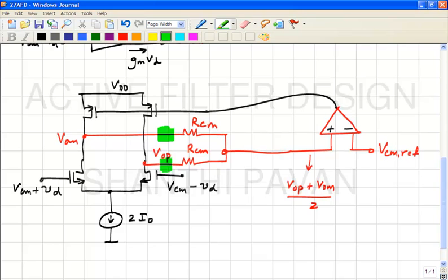So if you think of a strip of resistive material lying on top, there's always a capacitance between the resistor and ground. So the larger you make the resistor, the more the parasitic is going to pick up. So parasitics of the resistor are a problem. What else? Noise is not important because as you make the resistor larger and larger, in fact, the noise contribution comes down, isn't it? All right. What else?